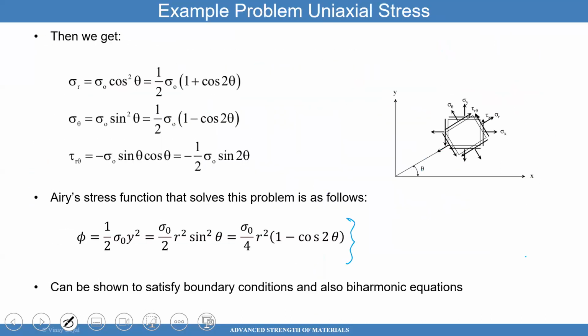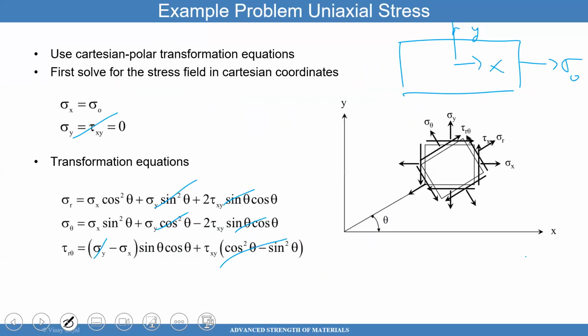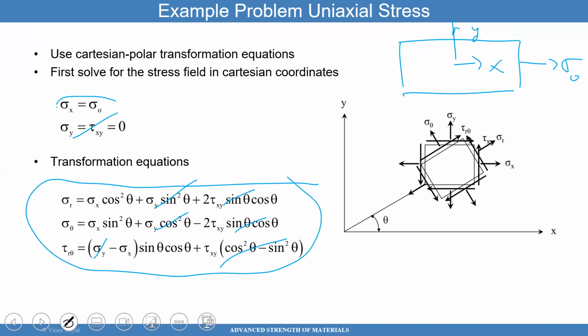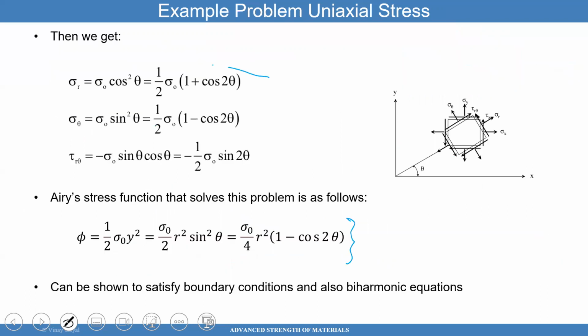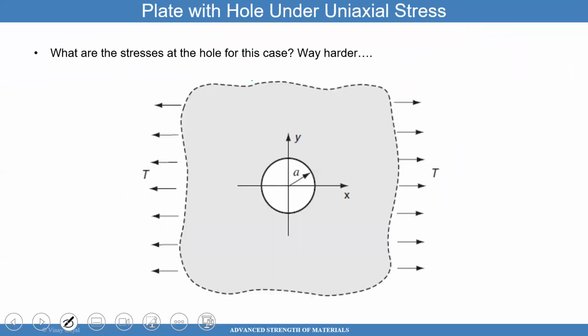And to recall, the coordinate transformations I'm talking about is the case that you see here, where the far field stress is sigma naught, and everything else is zero here, so you find that this is the state of stress in the polar coordinate system, and that's equivalent to the Cartesian coordinate system with sigma naught being in the x direction.